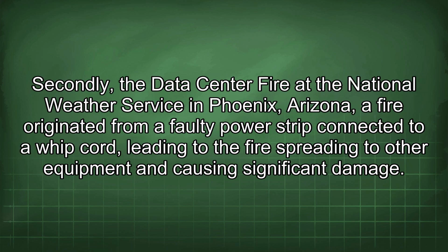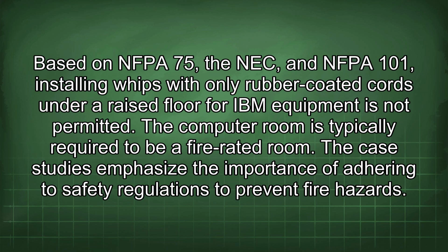Secondly, the data center fire at the National Weather Service in Phoenix, Arizona. A fire originated from a faulty power strip connected to a whipcord, leading to the fire spreading to other equipment and causing significant damage. Based on NFPA 75, the NEC, and NFPA 101, installing whips with only rubber-coated cords under a raised floor for IBM equipment is not permitted.